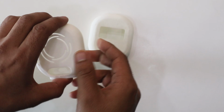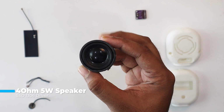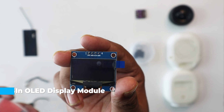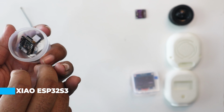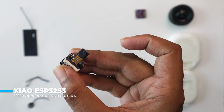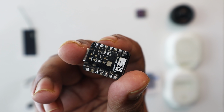Next, let's talk about the components we are using. For audio output, we are using a 4 ohm 5 watt speaker with a 40 mm diameter. For the display, we are using a 1.3 inch OLED display with the SSD1306 driver. As the brain of our robot, we are using the Zio ESP32 Sense module. The board is very compact and comes with a 3MP camera built-in as well as a mic built-in.